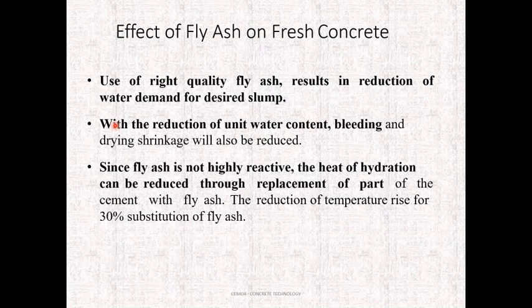The effect of fly ash on the fresh properties of concrete. By using the right quantity of fly ash, it will reduce the water demand for a given slump. With the reduction of unit water content, the bleeding and drying shrinkage of the concrete can be reduced. Since the fly ash is not highly reactive, the heat of hydration can also be reduced by replacing the cement with fly ash.